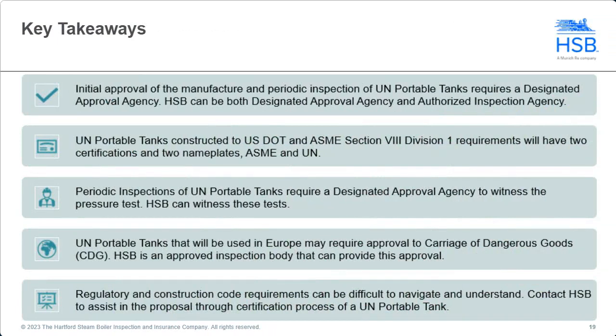Key takeaways from this presentation: one, HSB can be your delegated approval agency and your authorized inspection agency for UN portable tanks that are required to meet 49 CFR requirements. For US DOT and ASME Section 8 Division 1, you're going to have two certifications, one for ASME and one for 49 CFR, the UN.